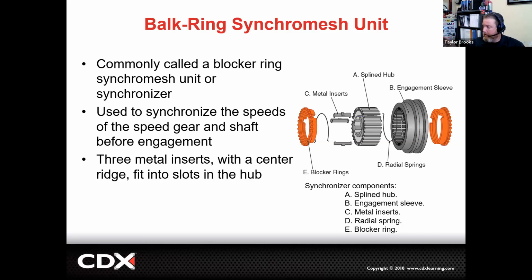You'd have to select the gear in a manner that you were doing it smoothly to where you weren't causing any damage. The transmission that I'm going to show you as a cutaway is an example of that. And we have a first gear and reverse are a slid gear design. Obviously, that required a lot of talent to be able to shift in and out of gears smoothly without doing any damage, as well as it was not very efficient. So we started to come up with these synchronizers that allowed for the constant mesh speed gears and allowed for smooth operation with one clutch engagement, disengagement.